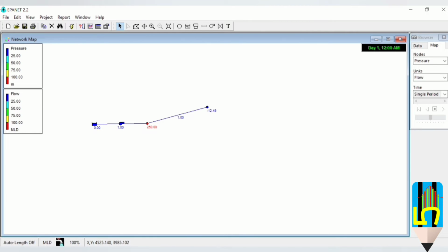Again, you cannot design pumps based on your whims and fancies. These pump curves that we are designing have to be provided by the pump manufacturer. But just to understand these processes, I am explaining it to you with a simplified version. In this design, again, we are not going to see the cost related aspects because there can be multi-dimensional analysis in softwares also. So in the next example, when we see a detailed Excel, we will see the cost related aspects also. Here our discussion is mainly related to the hydraulic aspect, rising mains, right?